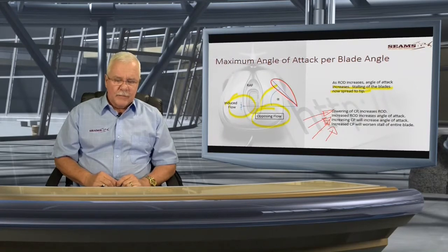Yeah, but no, wait now. The thing is, are you going to sit at 100 or 200 feet above the ground and figure out what the hell is wrong? Remember, if you lost your rotor RPM, you're already sitting with a high rate of descent that gets there. The rotor RPM in a hover was already there because you didn't have enough power available for the condition that you are in.